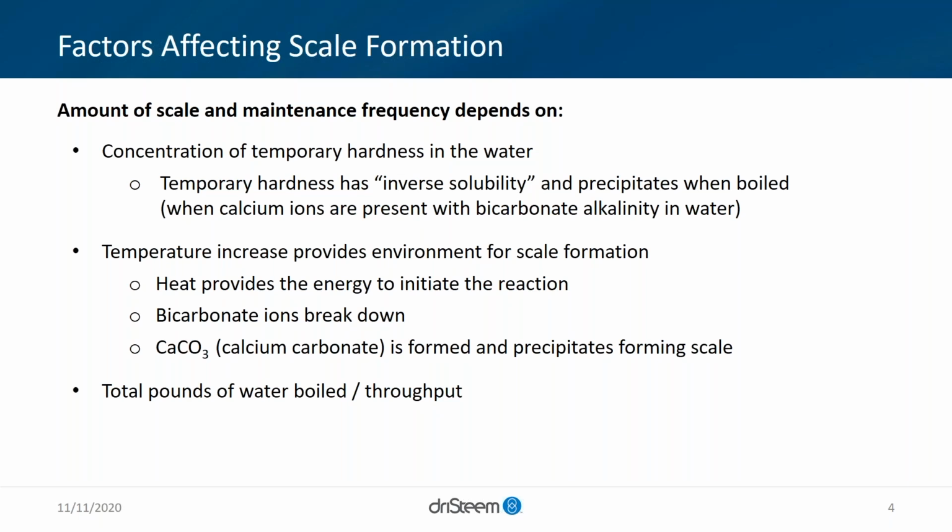So what that environment looks like, it's a combination of things. We're looking at the calcium, so hardness, we're looking at the alkalinity, and it's going to break down and form a scale. Obviously that scale's bad. I don't know how many on the call have had to take a service call where you had to scrape the scale off of a heat exchanger or chemically remove it. It's definitely not the most fun scenario. And the great news is it can be preventable, or the risk can be mitigated.